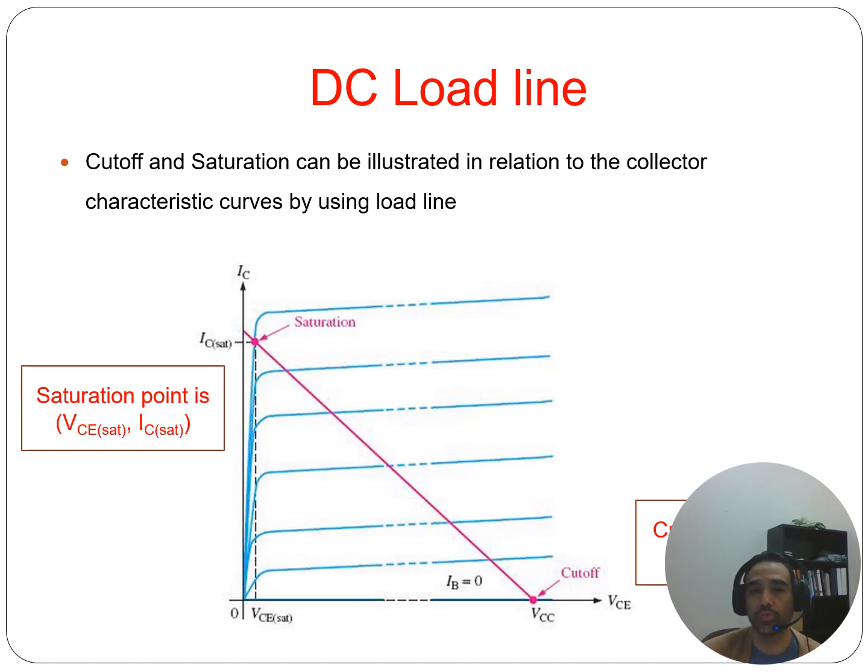Everything's still the same because KVL is still KVL, KCL still KCL, but VCE is going to be VCC, the source voltage, minus the voltage drop across that resistor, or I sub C times R sub C, right? That doesn't change. And remember again, VCC is just that supply voltage, whatever the supply voltage is, 12 volts, 15 volts. R sub C is that resistor on the collector.